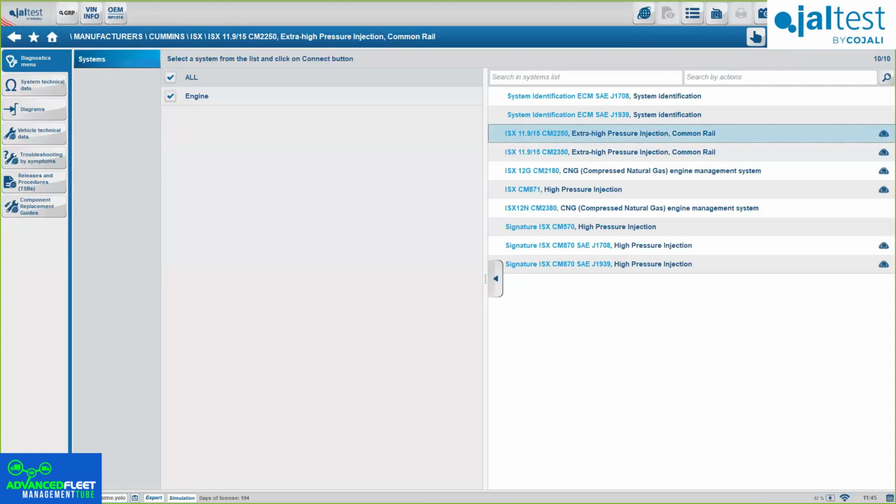Or, this is pretty important, and we'll do a webinar on this specific thing: if you already have a fault code, imagine the truck is on the road, there's a fault code, and you want to go service it, and you don't know exactly what's wrong with it, you can always enter the fault code here under manual diagnosis.